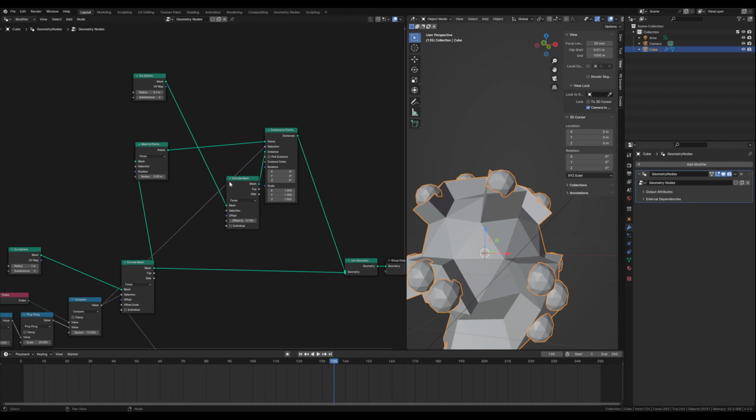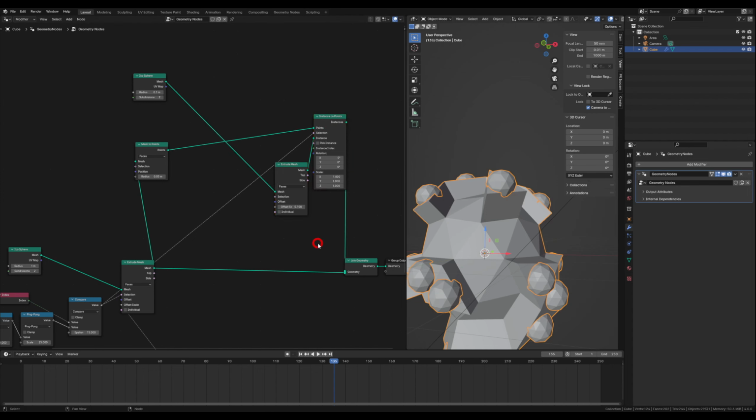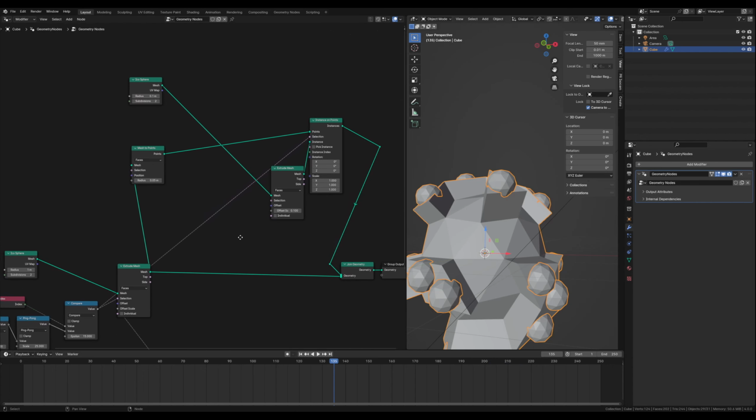And now we want to add, of course, extrusion of our new icospheres. So let's clean this a little bit here. Okay, you can add new point to this connection, shift and right mouse button and G to move, maybe here, G, and okay, to be more visually clear.